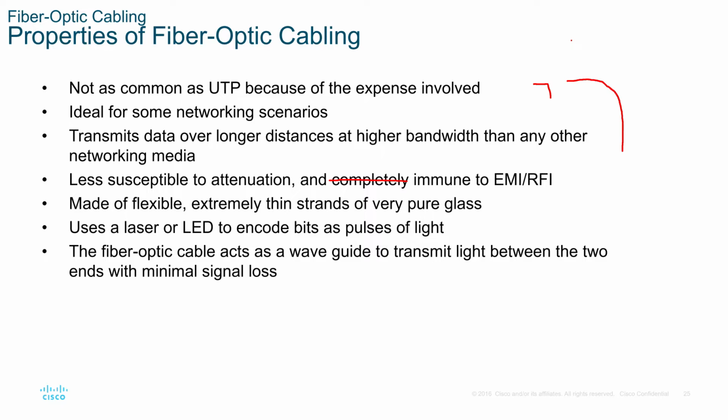But you never again ever look into the end. The power of the lasers or the LEDs will do damage to your eyes. The fiber optic cable acts as a waveguide to transmit light between the two ends with minimal signal loss. We still have signal loss.